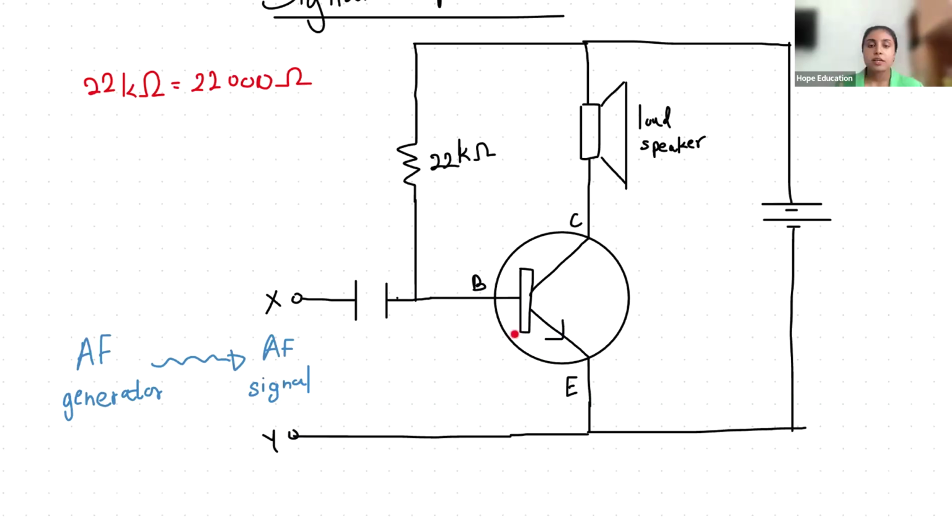Okay. So, yes. If the base emitter junction is not forward biased, the transistor will not work. Then we make a forward bias power source. Look at this very carefully. I will use a different color to show this. You know this is an NPN transistor. So base is a P semiconductor and emitter is an N semiconductor.